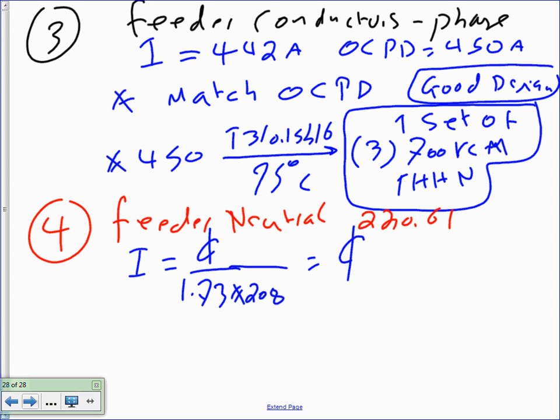So that's why you might end up with a mechanical panel that has no neutral. The panel does not need a neutral, just a 3-phase panel. The kitchen equipment, we shifted them. Remember, if you look at all the mechanical panels, if all your equipment does not have a neutral, then you don't have to size a neutral. You don't have to have a neutral, okay?